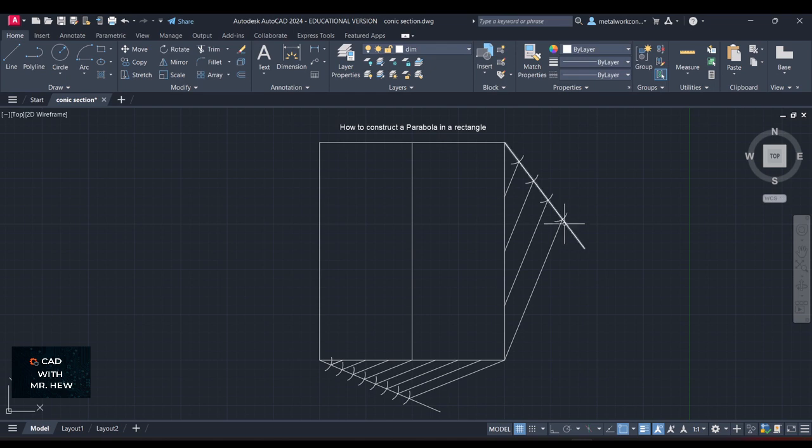As I said, align one of the set squares to this edge, put the other set square on the other side, and then use your left hand to hold down the other set square, and then use your free hand to slide the set square, and you would get these lines parallel. All right, good. And it's the same procedure you would do to get these 8 lines parallel.